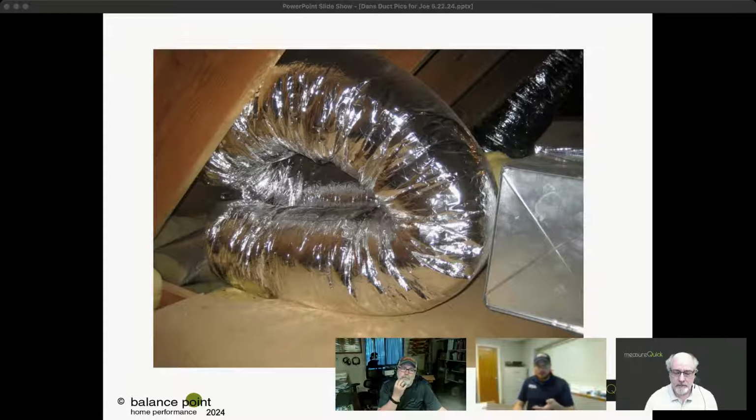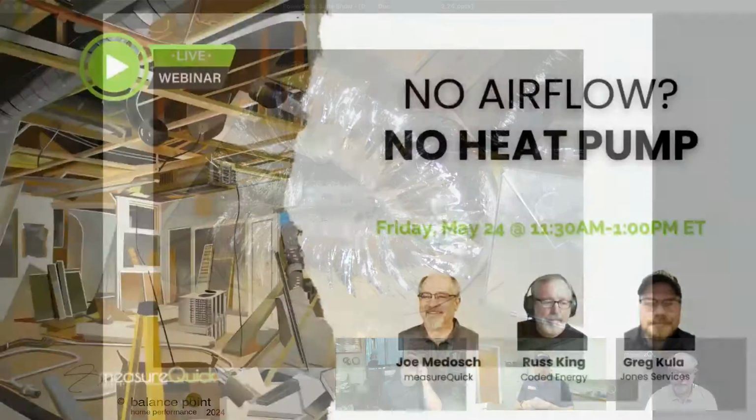Now, stuff like this, I'm sure some of my guys have done it in the past. Sometimes you don't have any other option, but that's where when we're sizing the ductwork and planning what we're going to do, we could take that into account. Like this one, you could work around this easily. But if there were trusses in the way, a chimney in the way, something like that where you can't get around it, or maybe the customer has storage that they don't want to give up or move, you've got to figure out what we can do that will work, but still keep the customer happy.